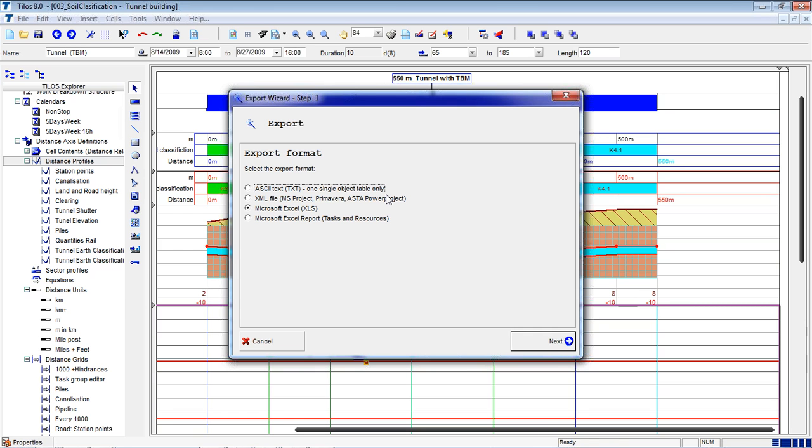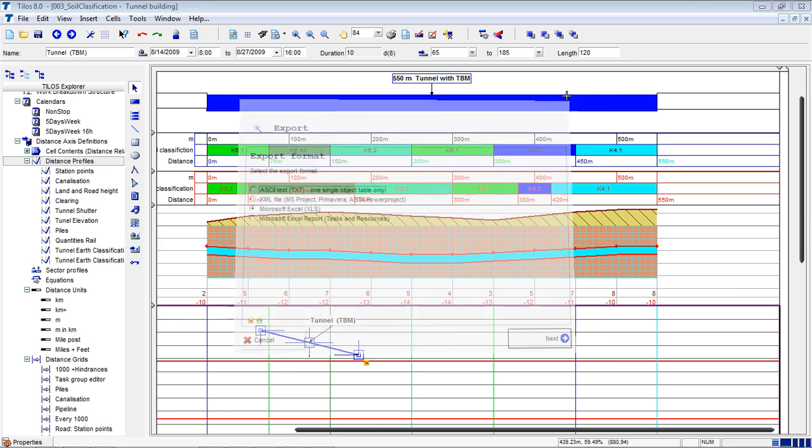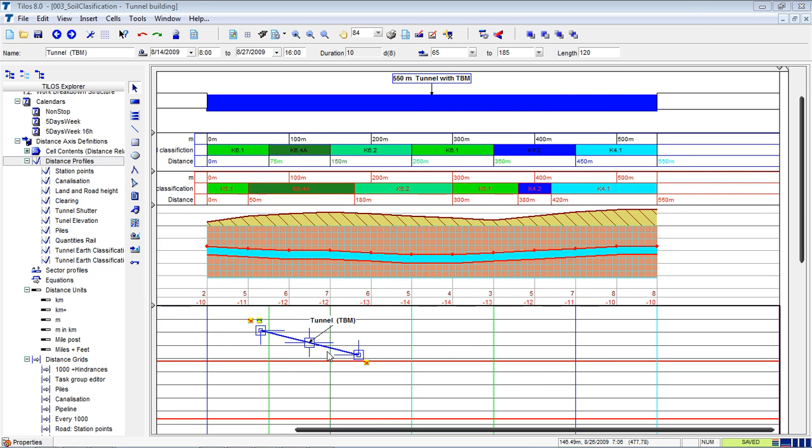Yes, it creates automatic user-defined fields like a start location, because in Primavera we don't have start location. That's why it creates a start location and end location. It is possible with Primavera, Asta, and Microsoft, or Excel. Both sides. Even if you prepare your plan in Primavera, we can bring that Primavera file into TILOS. By the way, I will show you maybe in the next example.